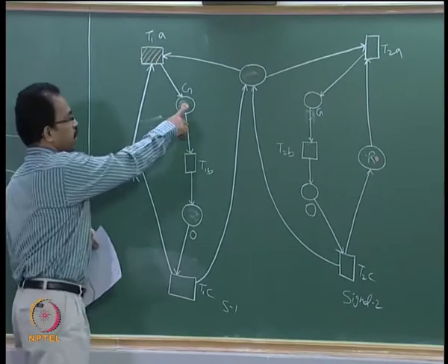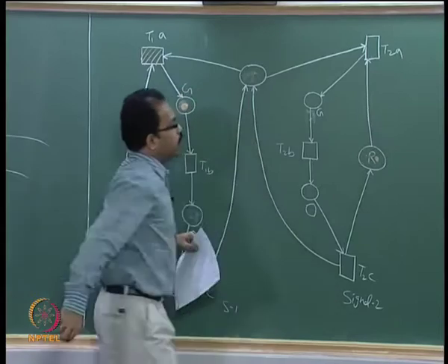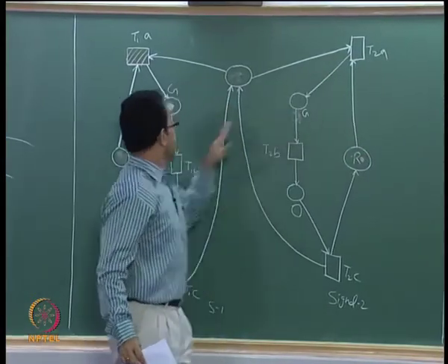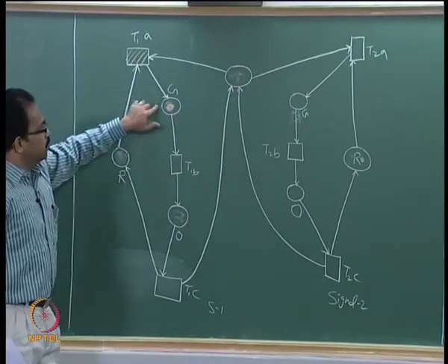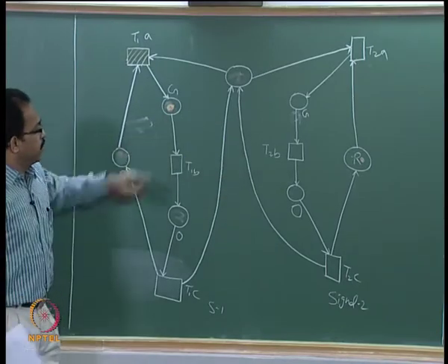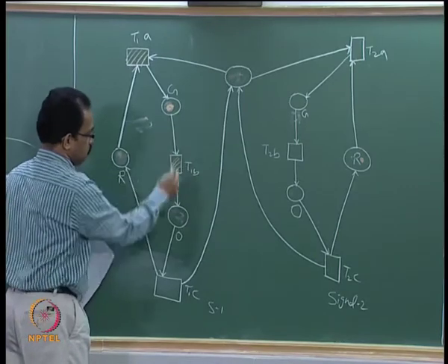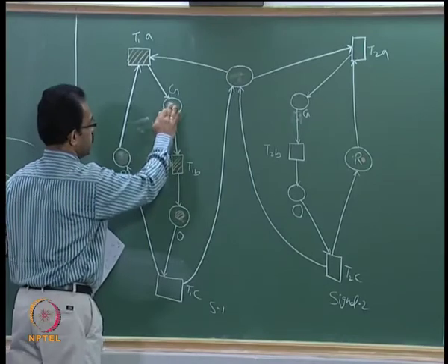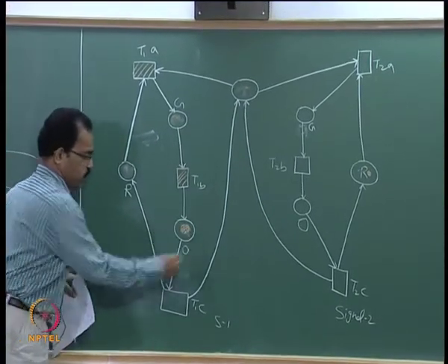Now this is green and there is no token over here, therefore T2A cannot change. So this transition cannot happen, that means this red cannot become green unless the token comes back to this position. So now this green is there, so the present position is that one signal is red, the other one is green. Now we have a transition here, suppose we go for the transition here, this token will be moved to here, that means orange will be activated. So this place has got an activation now, so the signal is orange now.